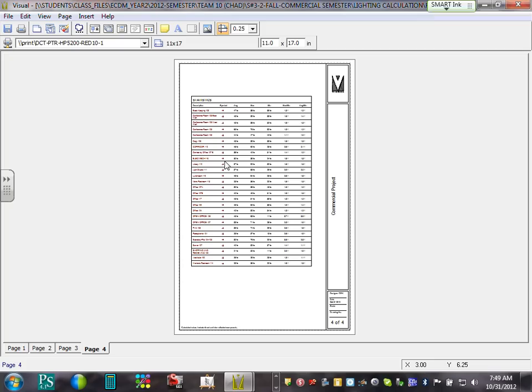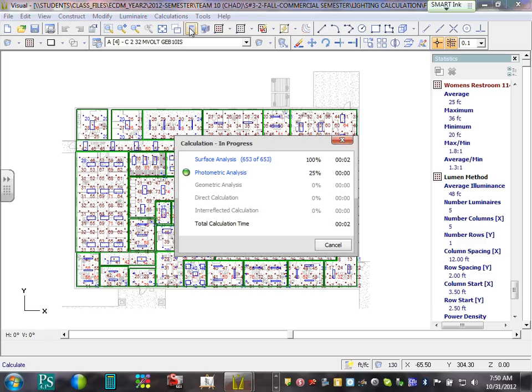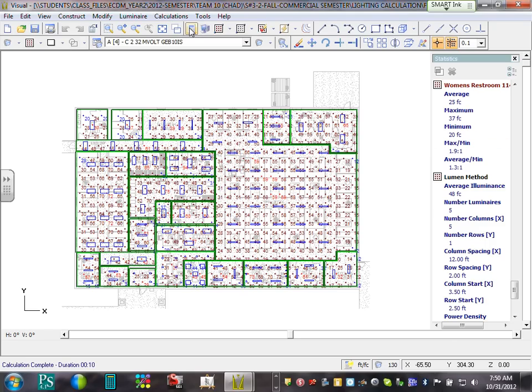Okay, let's take a step back and go get the calculation. Let me show you how you're going to do it. Now everything here, just close here, right here, close it, and you get back to where your calculation is. Before you do anything, can you guys go ahead and hit calculation? Calculate, calculate. Make sure your calculations are active for all the stuff that you want. Now, Darren, if there's any zones that you put inactive or invisible, you have to activate them. And you can do this at any time, guys. Even when you build all your sheets, you go activate them, they will show up.